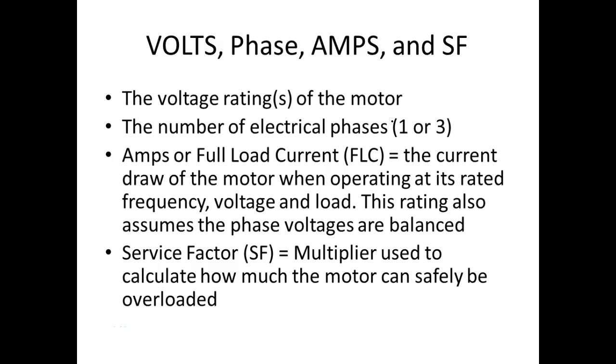Of course, that means that motor is going to pull a ton of current, you understand? A lot of times it'll kick an overload, because it depends on what it has to reverse, and a lot of times it takes longer to reverse than the overload is set to handle. You'll see that people do it, like on an attic fan. You flip it from forward to reverse, and you can hear it hum real loud because it's pulling a lot of current.